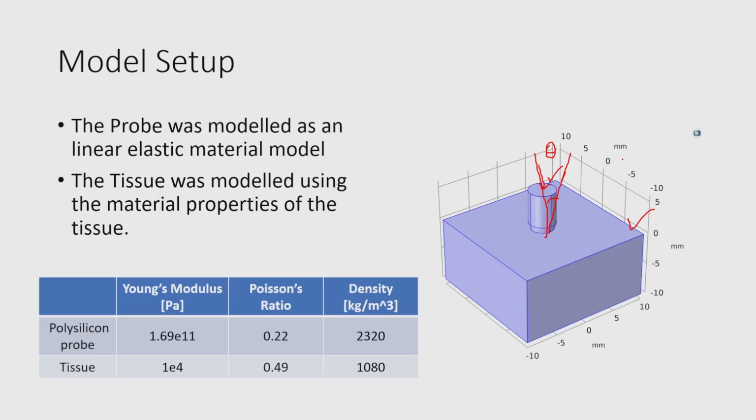Which angle is better, which angle gives more stress, and what the stress profile in the tissue is for different angles and pressure. If you know the threshold of the stress value which can cause pain, with that you can get to know how tight the headband should be, for example, or what angle of inclination the probe should be.